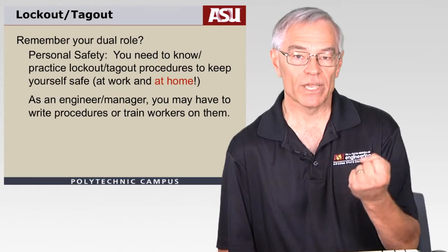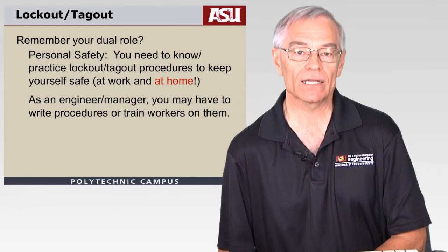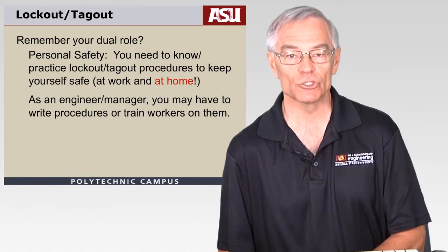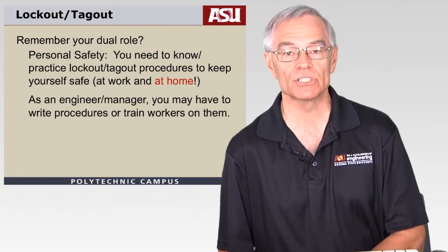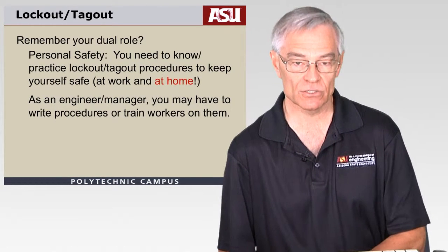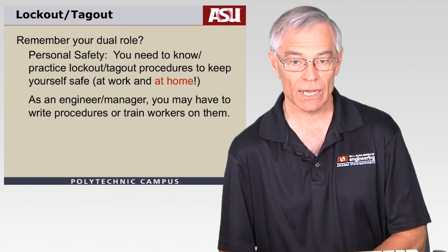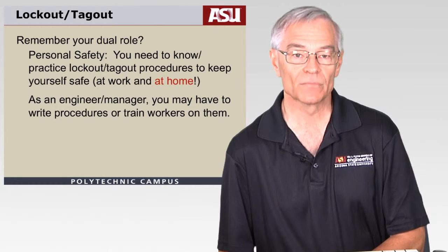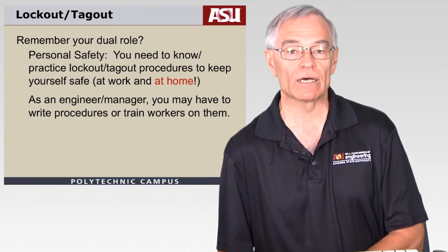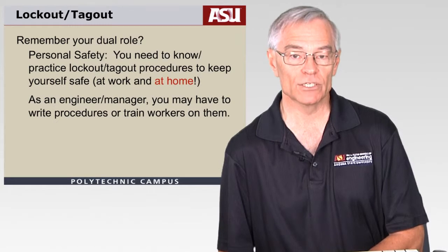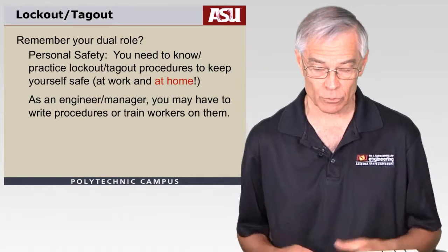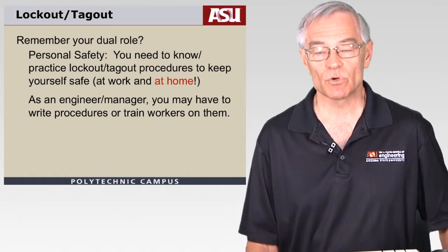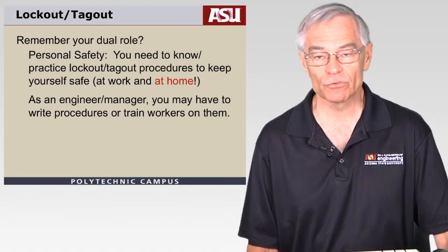Basically, they're often a way to lock out a machine via a padlock that you control, so that once you lock out that machine, nobody can turn it back on until you unlock the machine. And there are various devices to do that in addition to, of course, some sort of lock. But you may want to exercise that at home and at work. And you may end up writing procedures about lockout tagout, particularly if you're bringing a new process or new machine into your workplace, whether you've designed it or you're buying it from another supplier, and will have to create processes for your company or for your workplace.